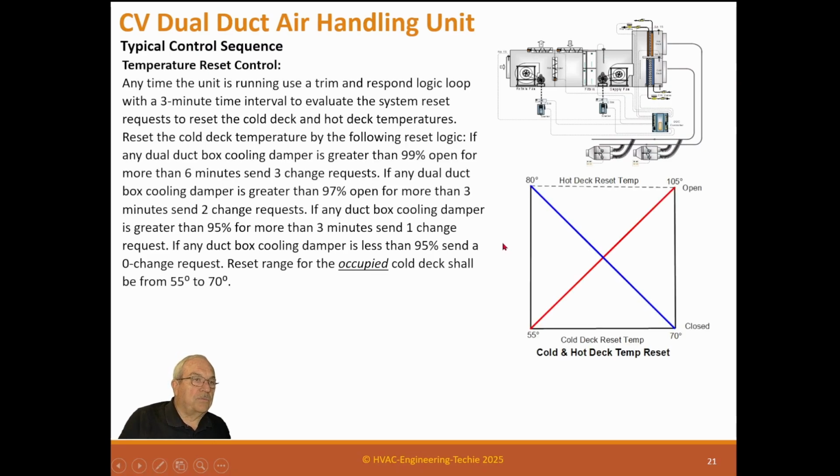All right, temperature reset control. Here we go. Anytime the unit is running, we use a trim and respond logic loop with a 3-minute time interval to evaluate the system reset request to reset the cold deck and hot deck temperatures. Reset the cold deck temperature by the following reset logic.